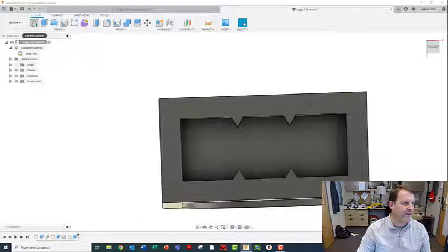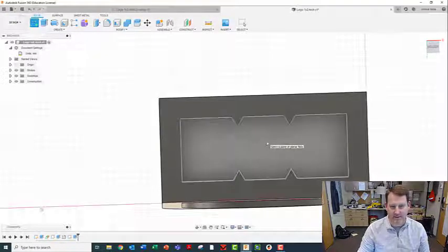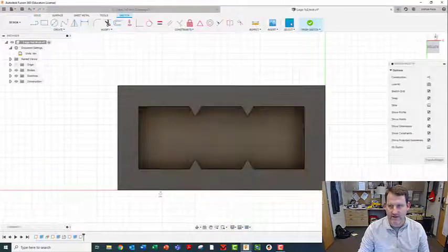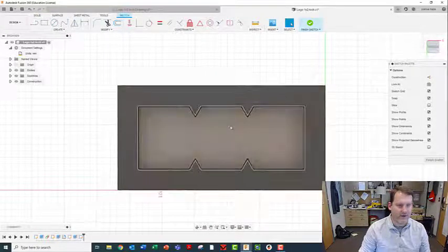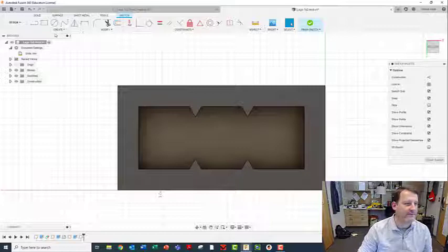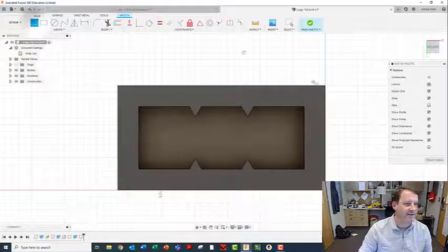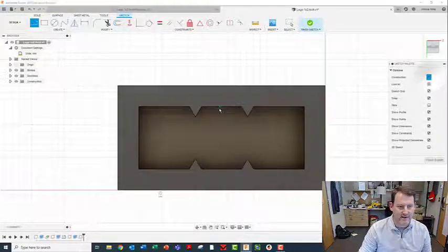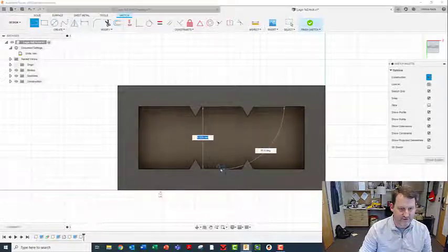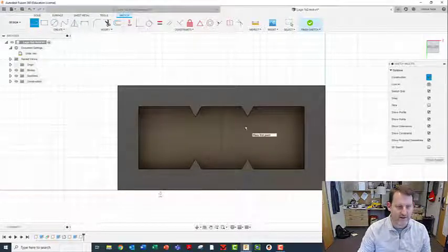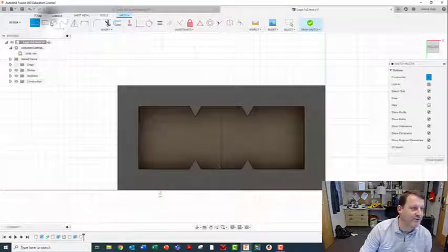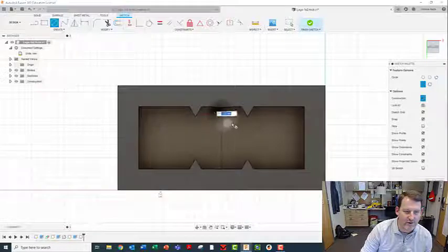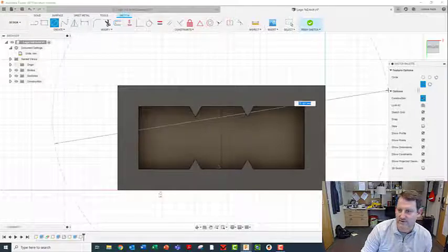Okay. So again, I'm going to create a sketch, and this time I'm going to create on this bottom face down here. That's actually inside my drawing. And I'm going to do a construction line because I want to find that center line again. I'm going to go right to the center. There it is. And then straight down, triangle, center line. Now the next thing I'm going to do is I'm going to put 2 circles in. And I know they're supposed to be, whoops, turn the construction line off.